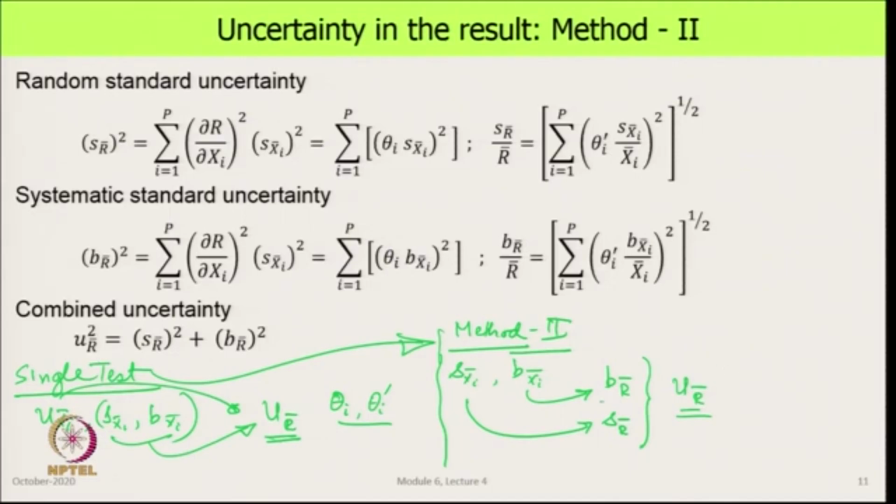We have contributions from systematic uncertainties, contribution from random uncertainties. By looking at these two numbers relative to this, we can say, well, what is it that is really hurting us? Is it the random uncertainty or the systematic uncertainty? And then within that, we can further break it up and then go backwards and say, which parameter is causing most of that.